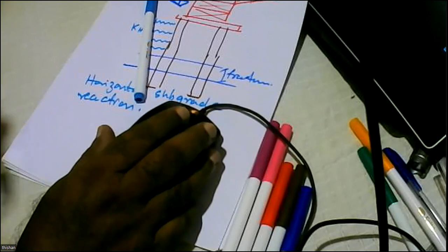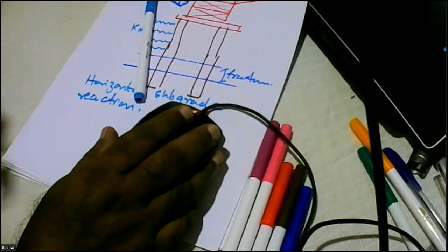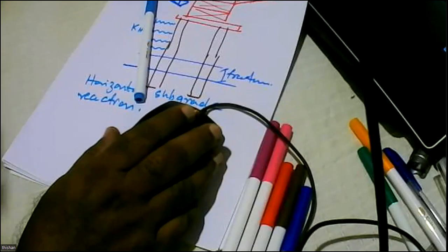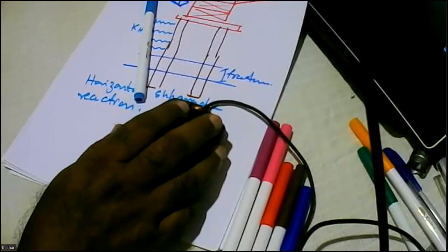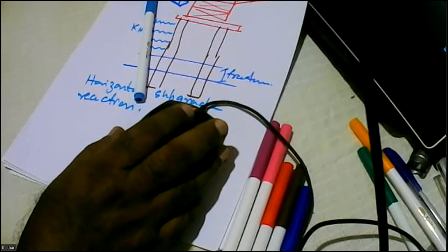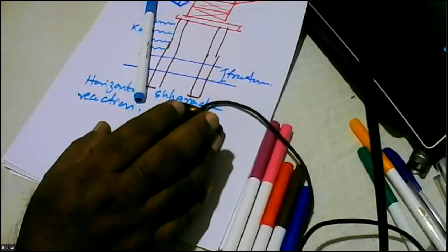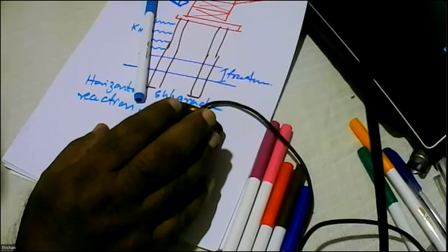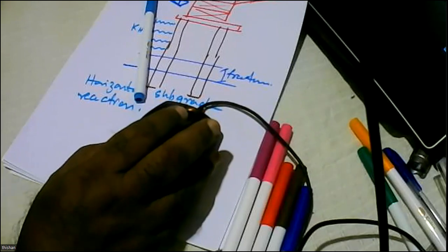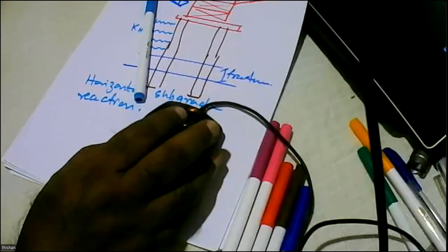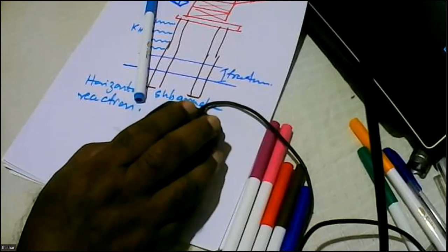So sometimes cohesion of soil is given as 5 times N, and I prefer to use 4.5 times N. But many geotechnical engineers use the cohesion equal to 5 times the SPT value. But if the SPT is like 2 to 4, you have to be very careful, because sometimes the SPT that is reported may be misleading. When it is greater than 4, generally, you can rely on the SPT value.